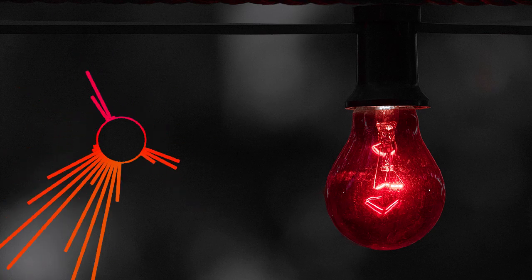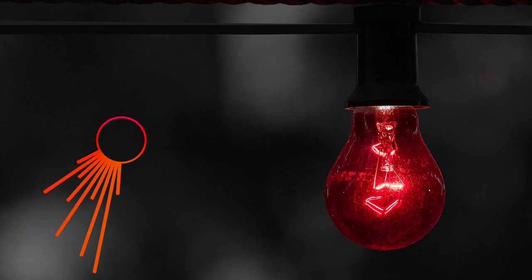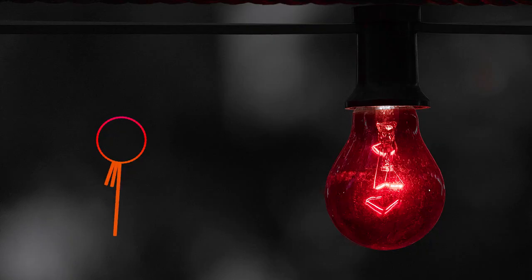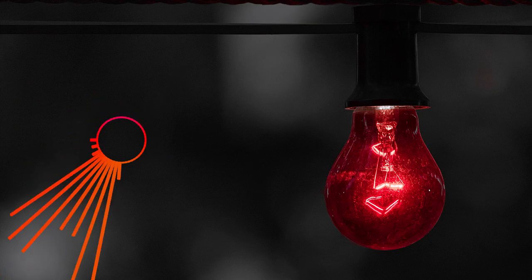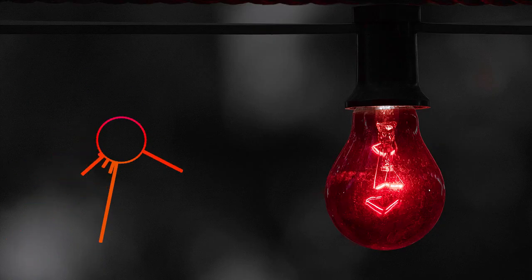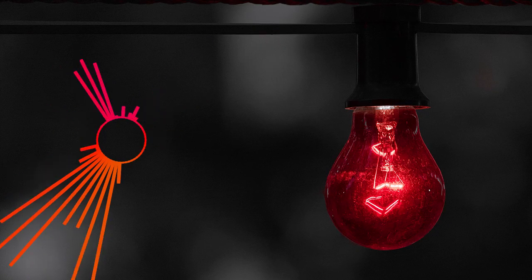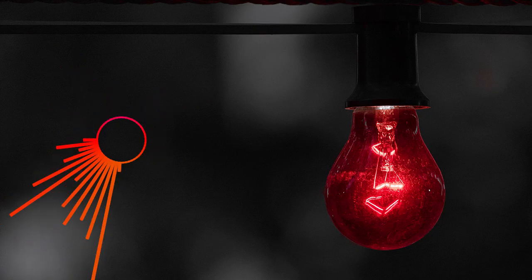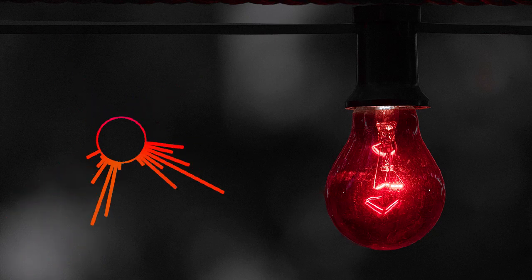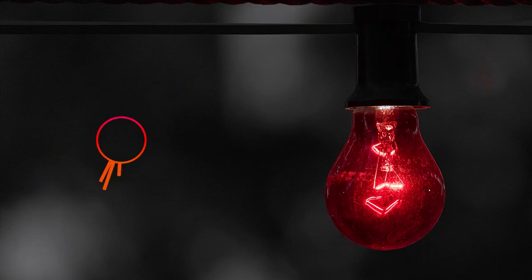That's why lighting designers use photometric layouts. They take light measurements, create diagrams, and use software to figure out the best placement and fixture type. The result is more even lighting, fewer hot spots, better energy efficiency, and a cleaner, more professional appearance. So, even though LEDs are easy to install, design still matters, especially in commercial and architectural settings.